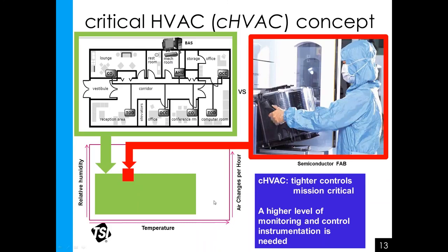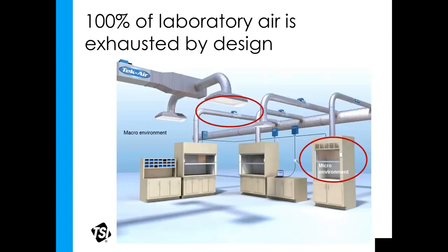These are not exact numbers, but the purpose here is really to show this situation and this situation are completely different as far as relative accuracy, relative precision, and requirement and instrumentation goes. I wouldn't use the same instrument to measure lobby temperature here to measure the proper semiconductor fab temperature over here. They just don't work in those types of applications. So that might be a different way, in my mind, to view critical versus non-critical.